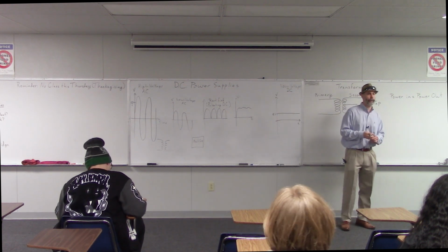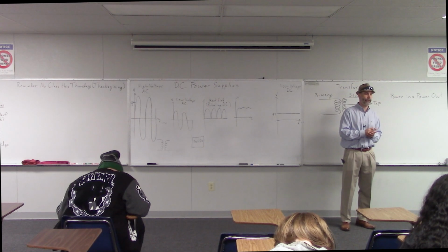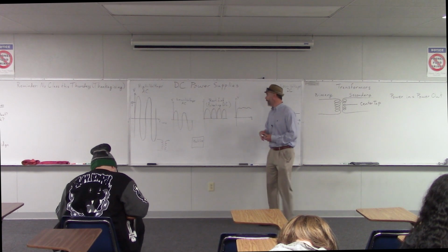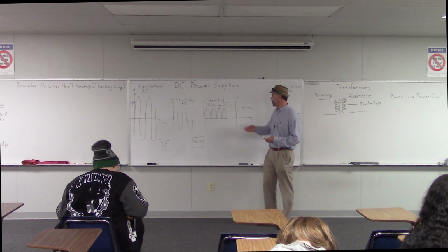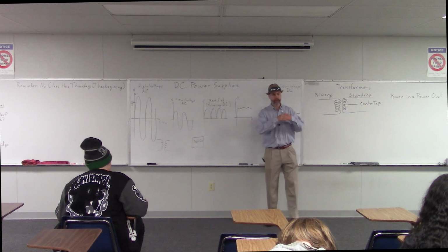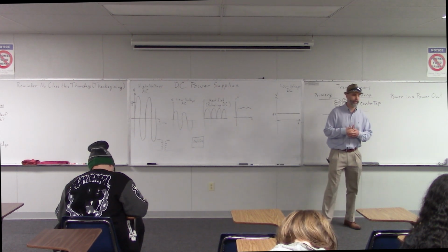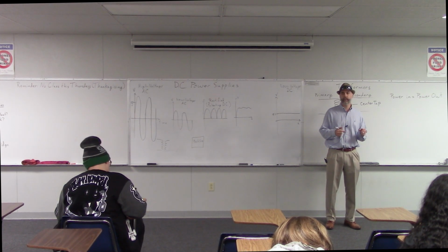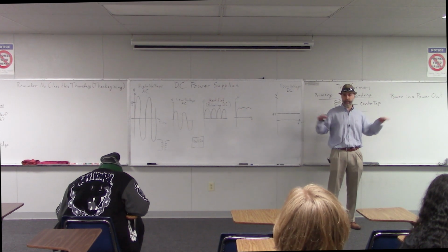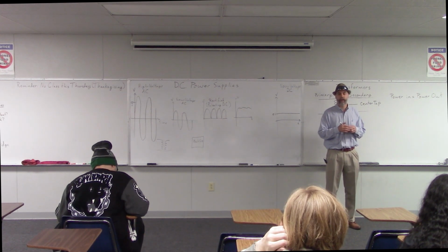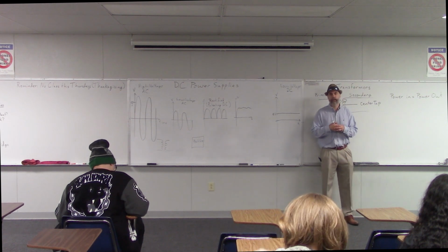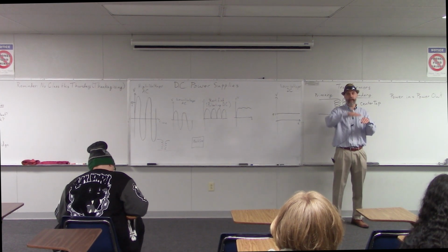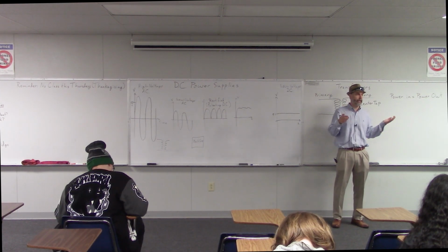So we've talked a little bit about filters in the past. We said that filters allow certain things to go through, but they block out other things. So in this case, we would use a low-pass filter. That allows low-frequency signals to go through, and it blocks out high frequencies. Remember, what was another name for the lowest type of frequency? The lowest frequency you could have, what's that? Ground, right? So ground would be an example. The lowest frequency that you can have is something that doesn't change at all. It never moves. And so that's a DC signal, and that's what we want.